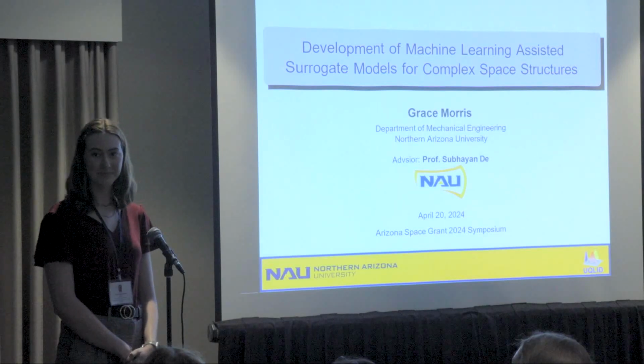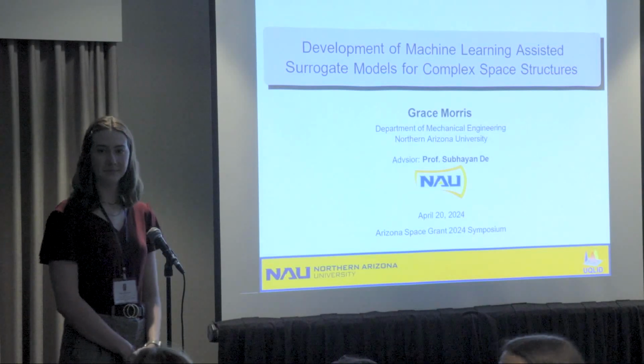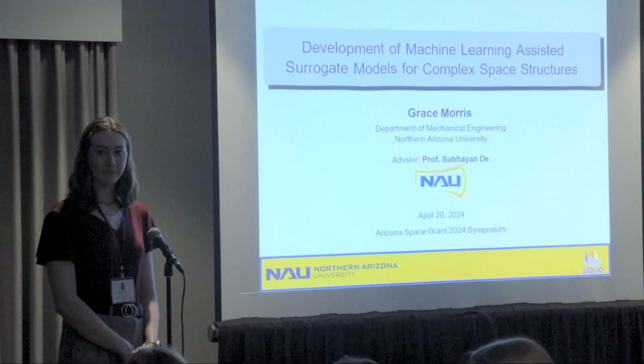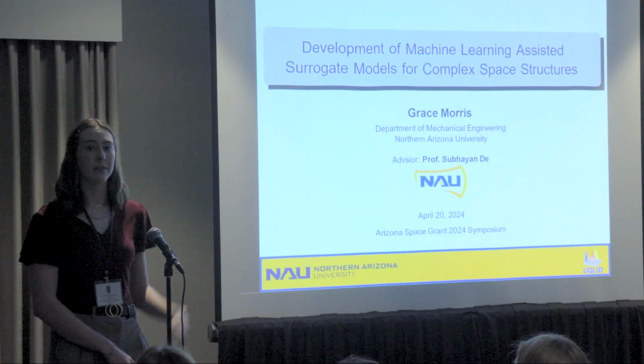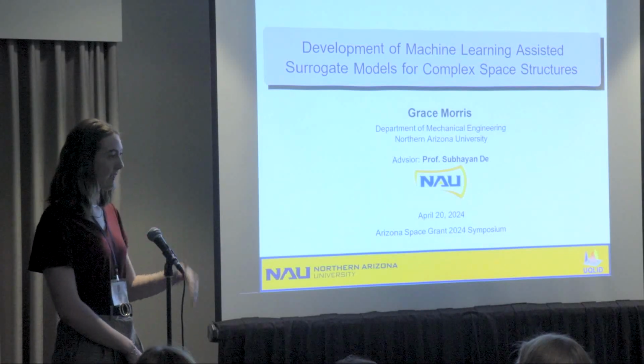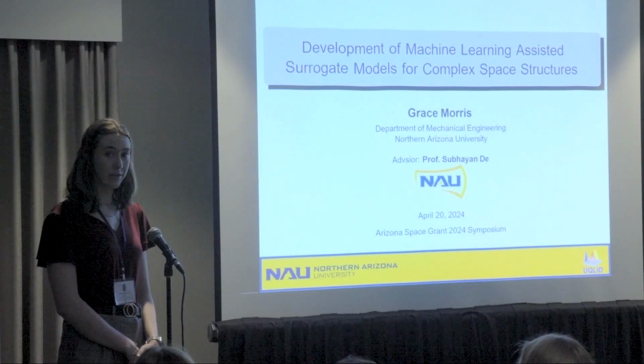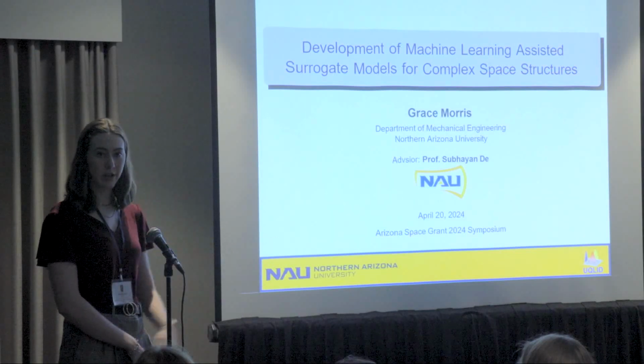Assuming you have different grounds for your domains, do you have a way to deal with a potential difference that could develop across the grounds? We do. I don't know if you guys saw on the last design, but we actually have an analog ground for the front half and then a digital ground for the second half. And between those, we have Schottky diodes to help minimize voltages being transferred between the two.